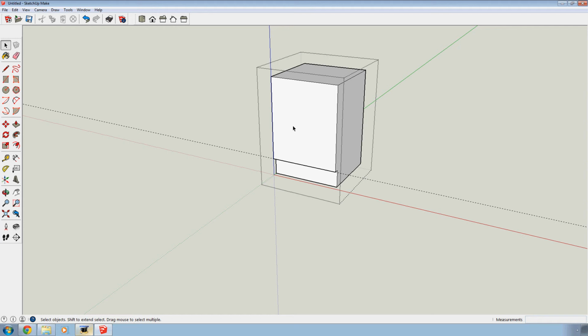Now I do shaker cabinets, so I'm going to draw a recess on the front of this. We're going to pretend that this is a highline unit. Highline is kitchen designer jargon for a unit which is basically a cupboard and has a door going from the top to the bottom. So I need to draw the recess. I can use the offset tool, which is this one, also F, click on the surface. If I enter, in this case I'm going to enter 75, press enter, then I can use